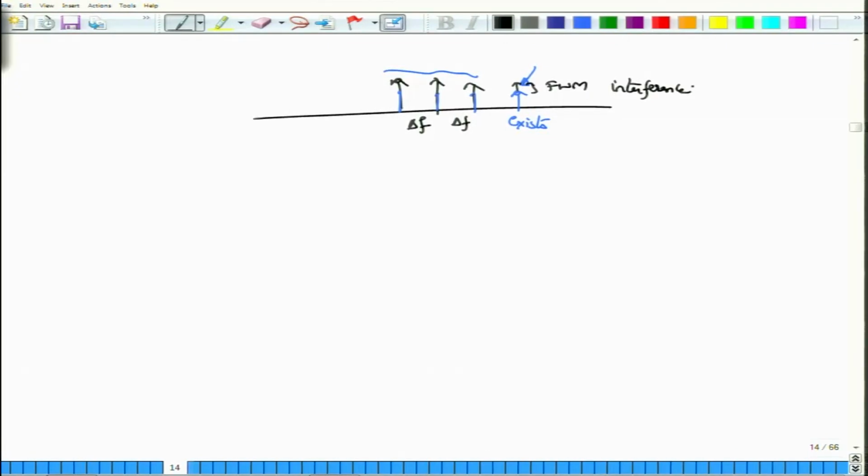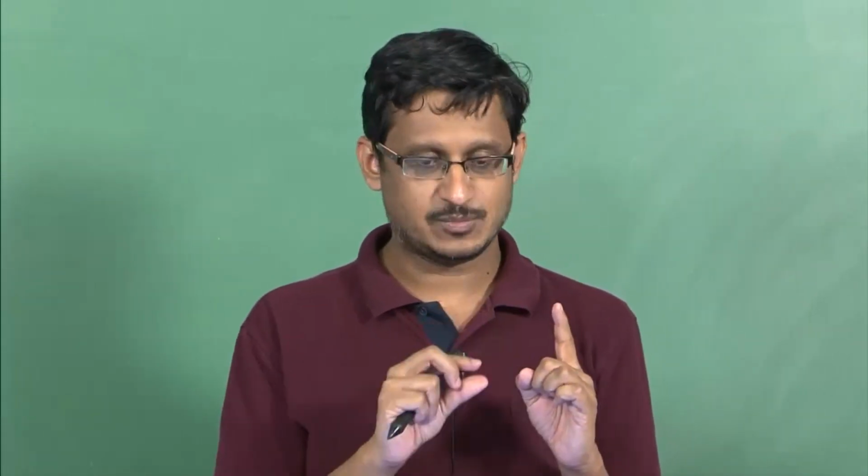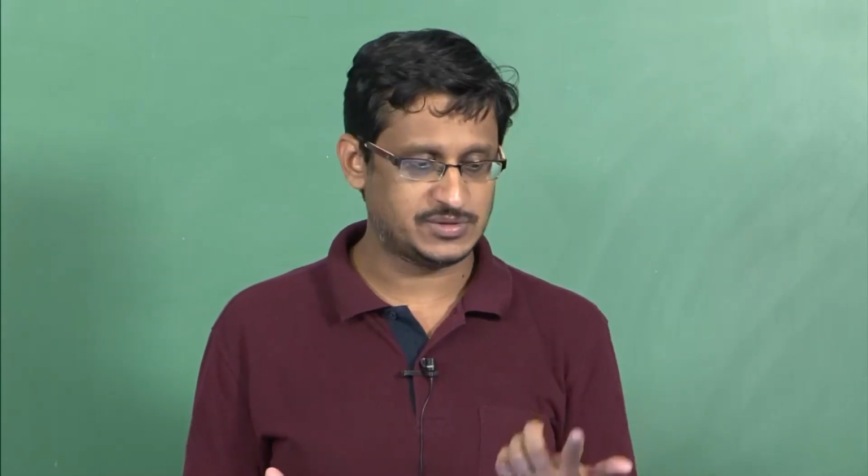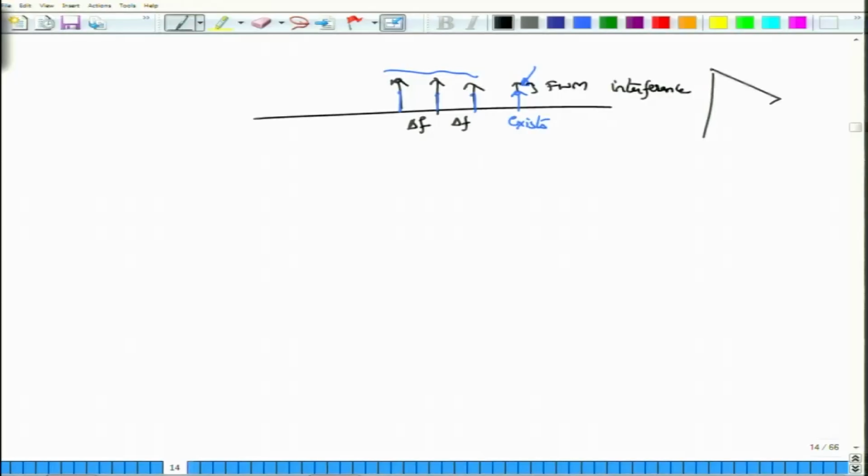This is very similar to the interference that occurs in a wireless communication system when you have a strong signal and a weak signal. The strong signal will start to interfere with the weak signal, and if you present both of them to the amplifier, the strong signal will actually eat up a lot of power, while the smaller signal at a different channel will not usually have anything. So, this is called a blocking signal, and exactly the same thing happens in four-wave mixing. Because these channels are usually followed by an optical amplifier, the channel which has a higher power will start to saturate the optical amplifier.